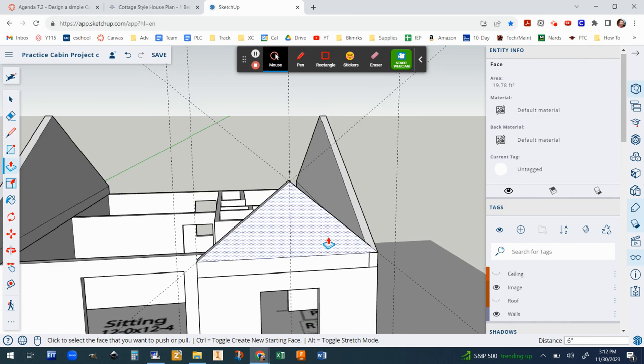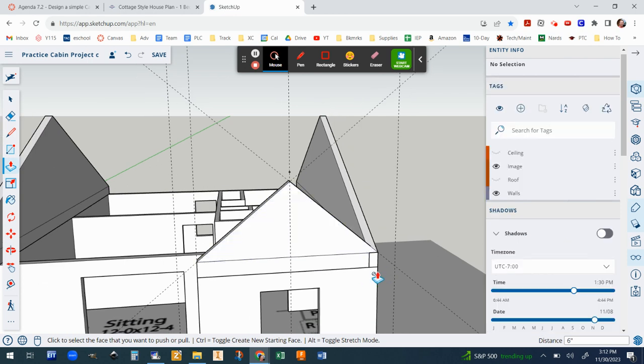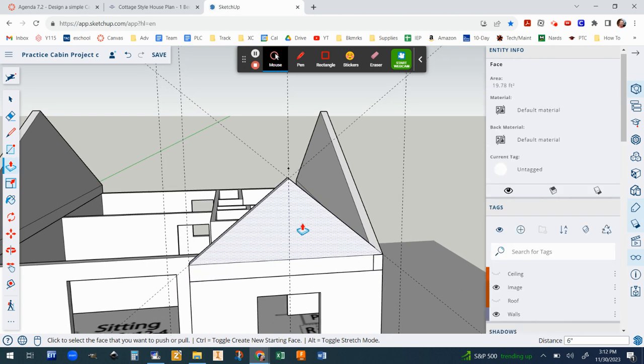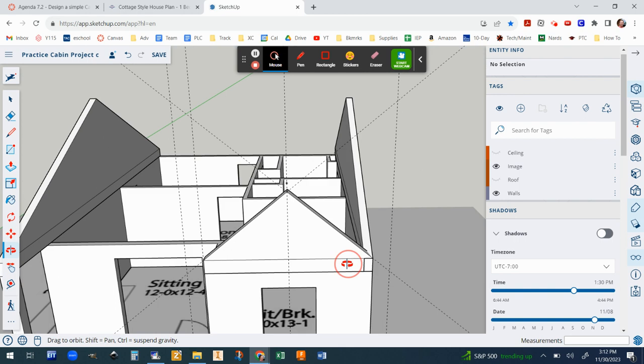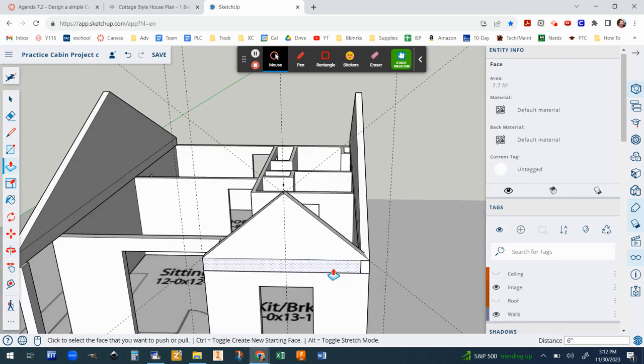Okay. So it's important that you note that in construction, you want all your overhangs to be perpendicular to your outside walls and to make sure that they're all the same distance. Otherwise, your roof lines are not going to match up. All right. So we were careful to do that. So we shouldn't have a problem. But, hopefully that'll be the case.